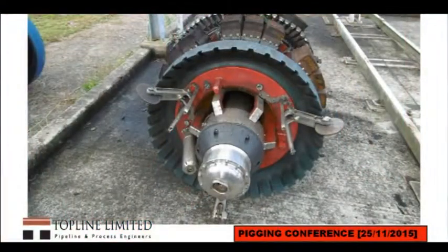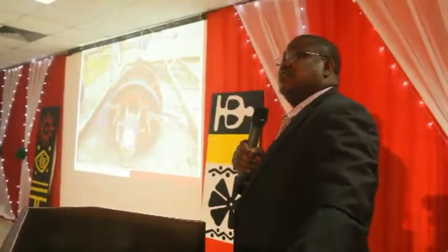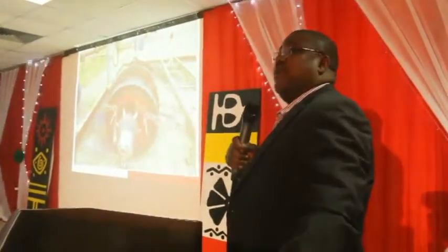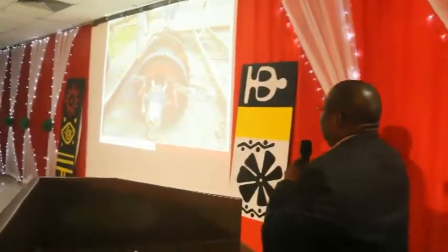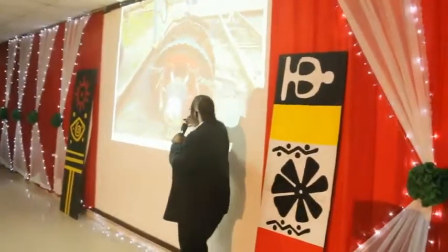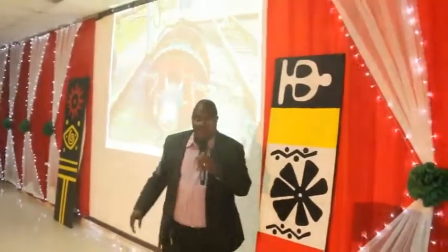Those are the pigs. They are longer. As you go from the smaller diameter lines, you get longer intelligent pigs because where to mount the instrument is a challenge. Next. When you move to higher diameter, this is about 40 inches, 36 inches, these ones get more compact, and you can see the odometer that I was talking about, and where the central processing unit is. When launched, it has to be activated for it to travel. Mounted with sensors and magnets with drive cups.